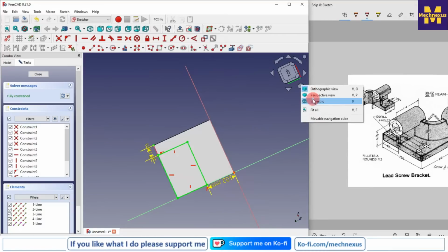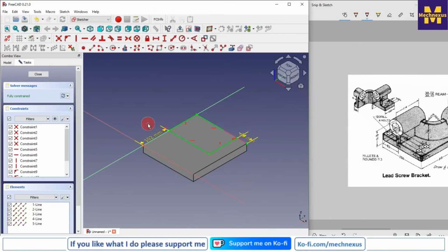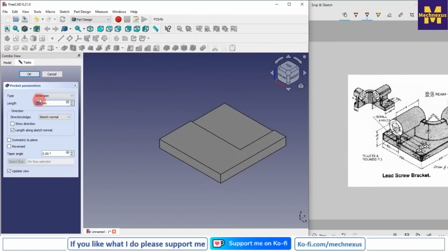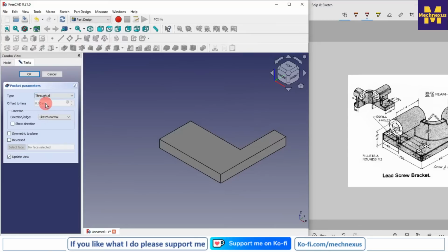Now I will switch to the isometric view. Now I will close my sketch, click on the pocket tool, and material I will say through all.